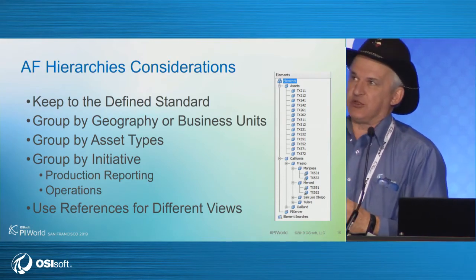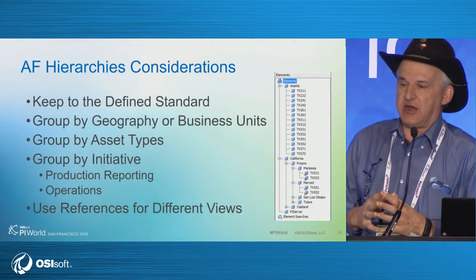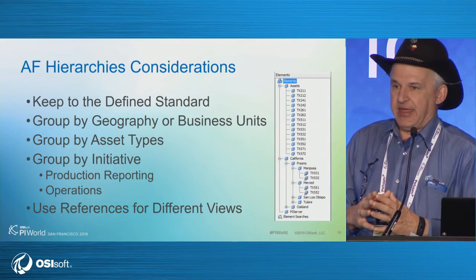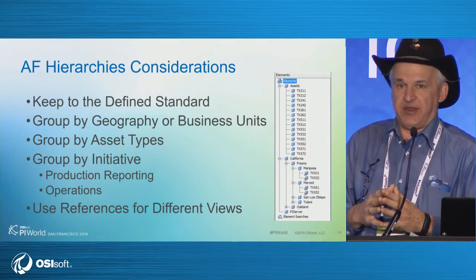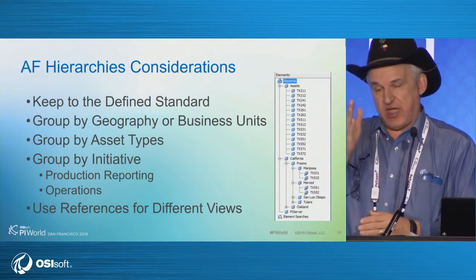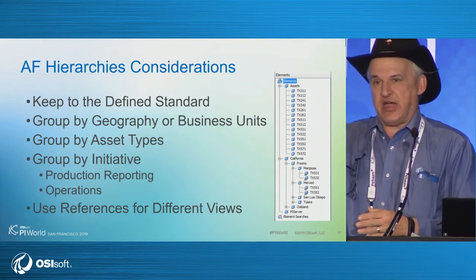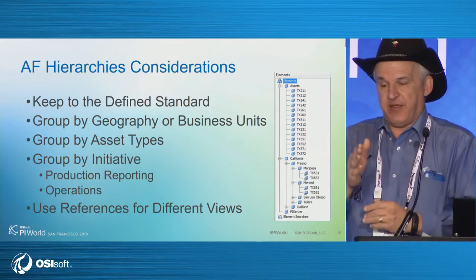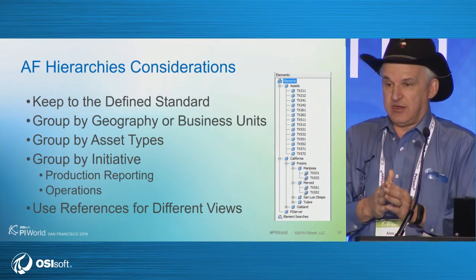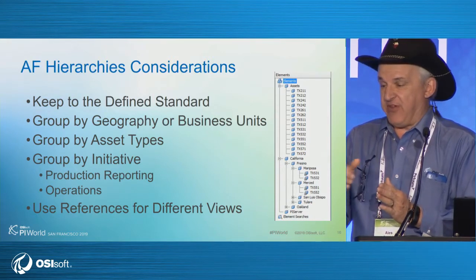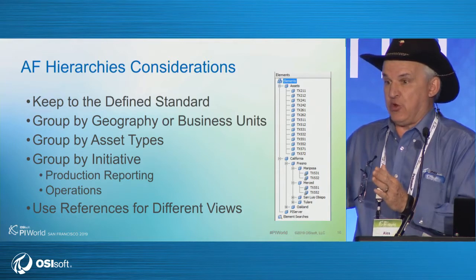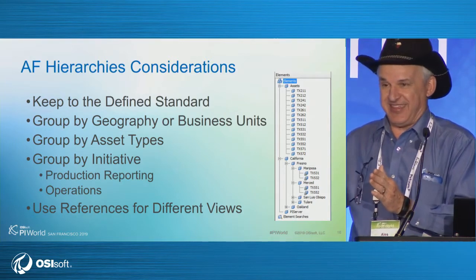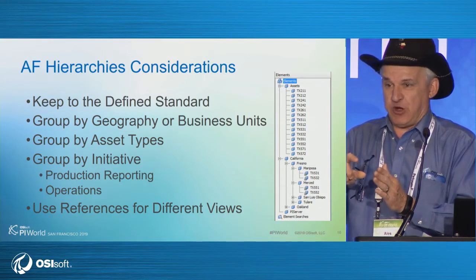So some considerations to think about when you're building hierarchies is, again, keep to a standard. So I'm going to build an S95 or whatever standard is. So every level is a defined thing. Right? So let's say you have a hierarchy of like 5 or 6 deep, and level 3 is a unit. You never, ever, even now, as I'm at the place where I don't really have a thing called unit here, I still define a unit in the other template, whether it's a fictitious one or not.